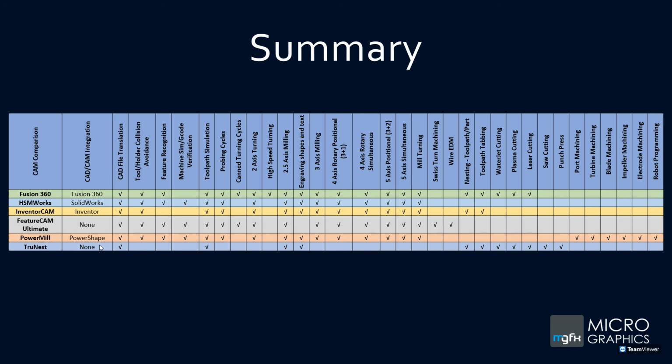So if you produce a lot of bar stock, like round bar, square tubing, angle iron, you need to cut a lot of that down to size. TrueNest can nest that into linear nests for you, or even sheet metal. It can nest so you can use the optimal amount of material on your sheets. And it also has stock control capabilities and ties in with your ERP to control how much stock you have left, and also control of dropouts, the smaller pieces that are cut that are not used or supplied.